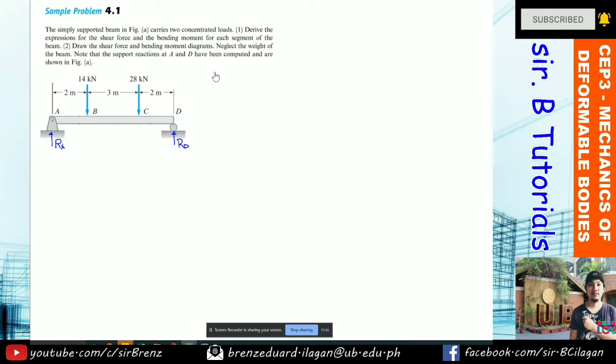The equation for that, assuming that all counterclockwise moment is positive, summation of moment at A equals 0. So we have here 2, 3, 2, so that is 7 RD, equals 14 multiplied by 2, and then plus 28, and then multiply by 5.